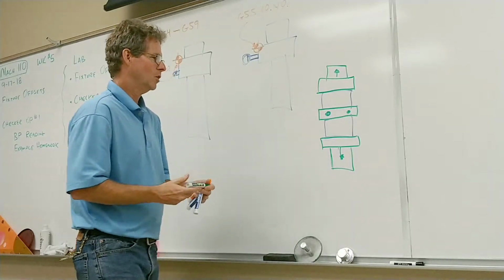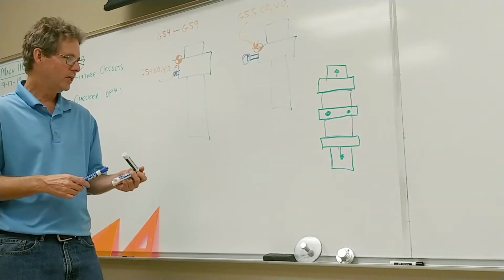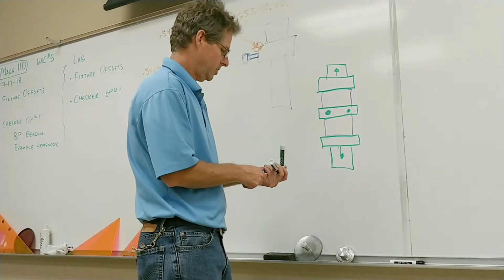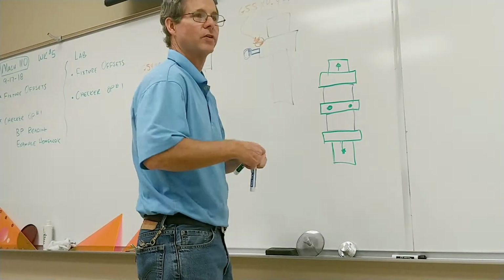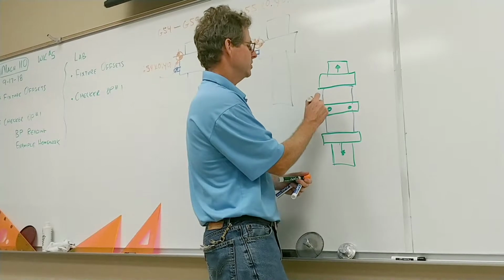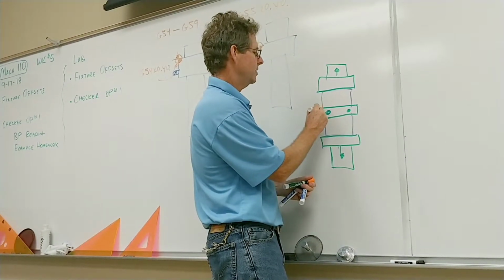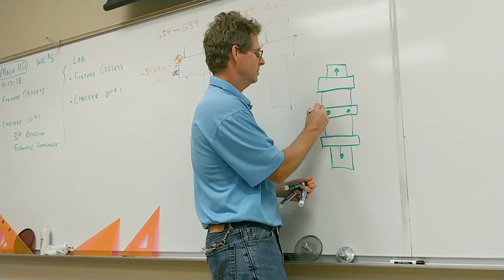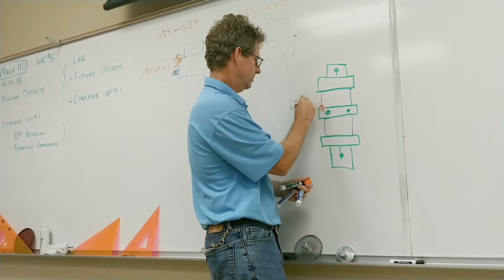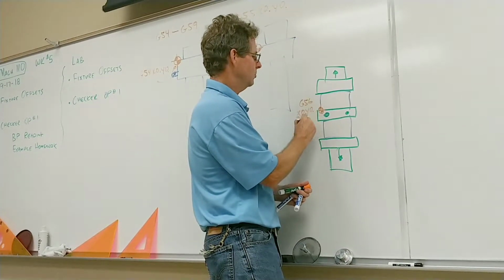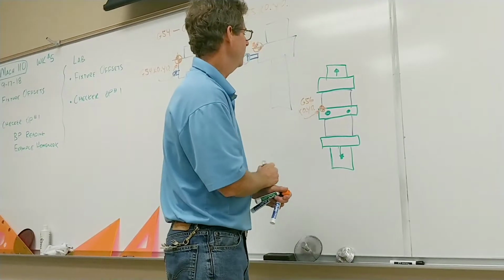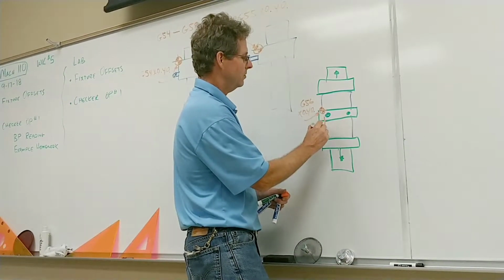Okay? So on a vise like this, you might want to say, okay, I'm going to make G50. Well, I've got 54 used, 55 used. This is the same machine. I'm going to say G56 is right here. This will be my G56 as X0, Y0 position. And then I might put my G57 right here.